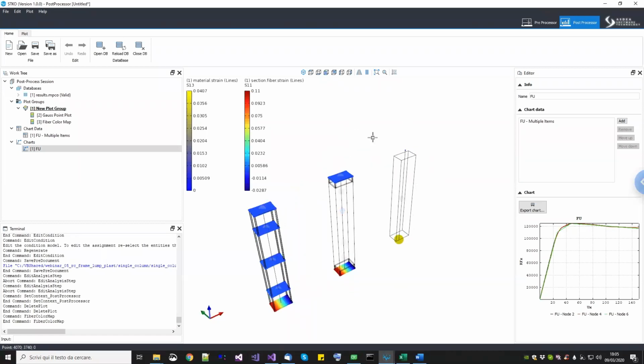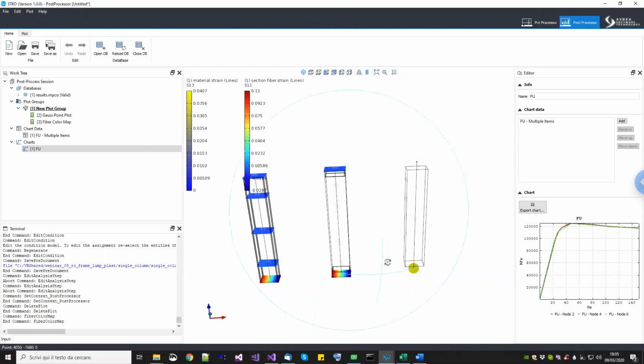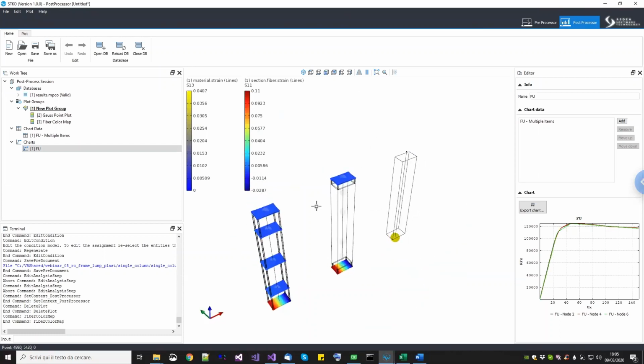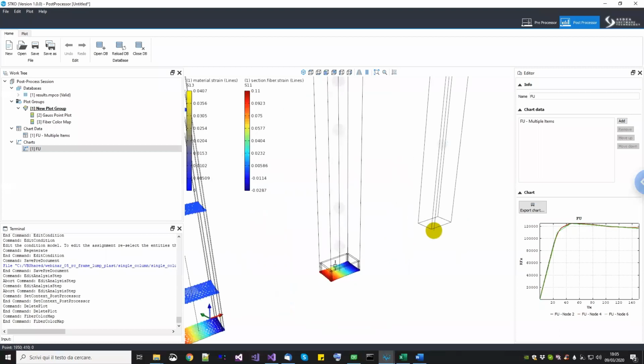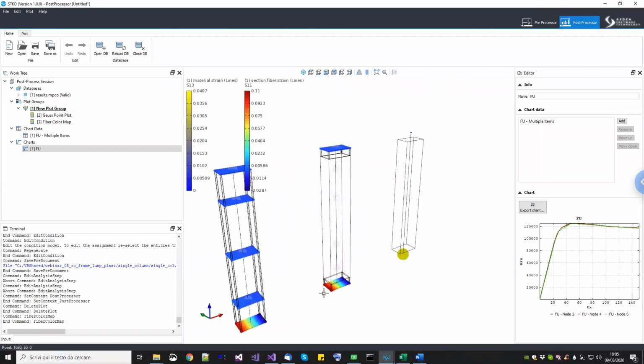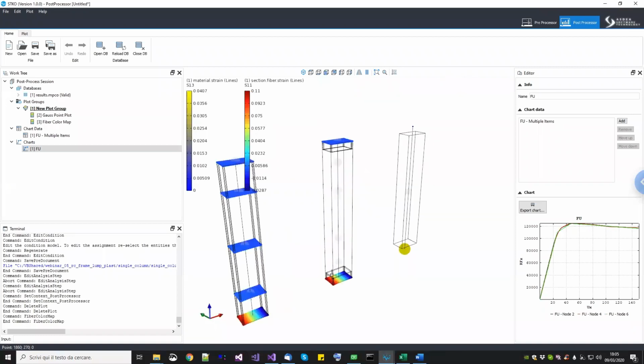As you know, in OpenSees, the lumped plasticity approach can be achieved in 2 ways. We can either use the beam with hinges model that is available in OpenSees, which uses the fiber cross-section, so there is the advantage of taking into account the coupling between the axial load and the bending response. But this nonlinear response will be available only at the 2 ends of the beam. So this one is basically a lumped plasticity approach over a finite length, which is equal to the plastic length.